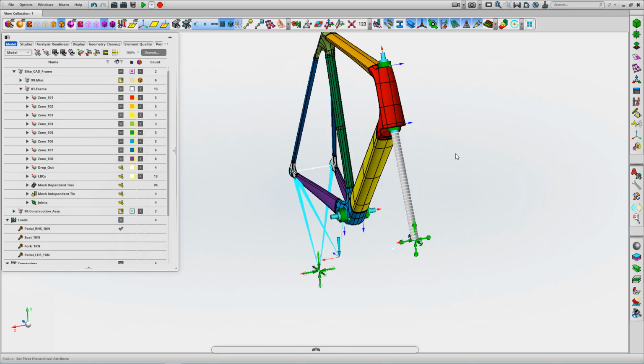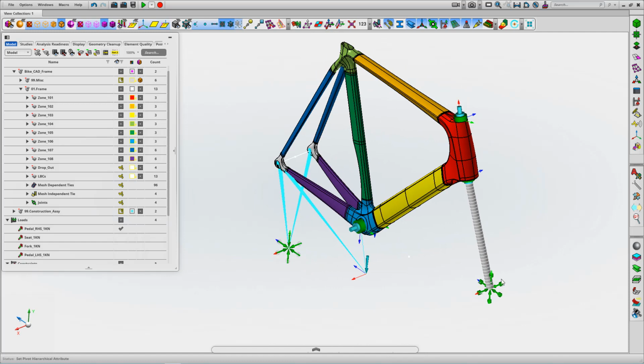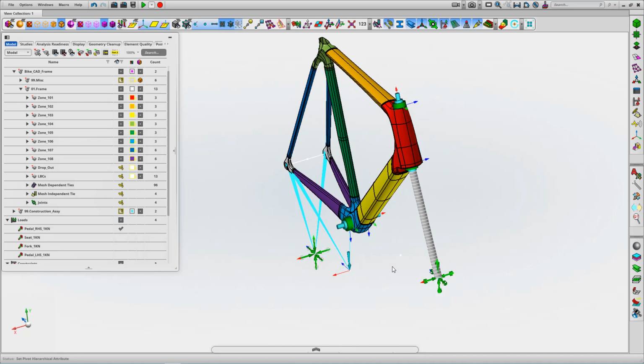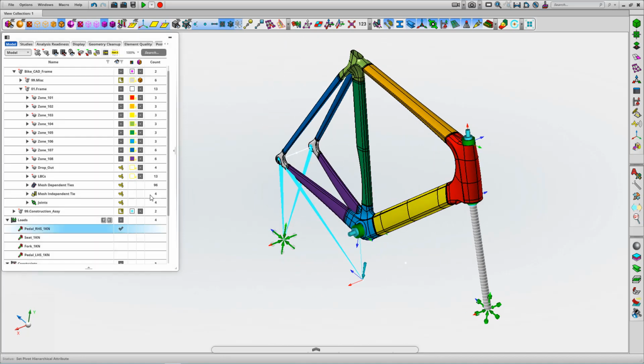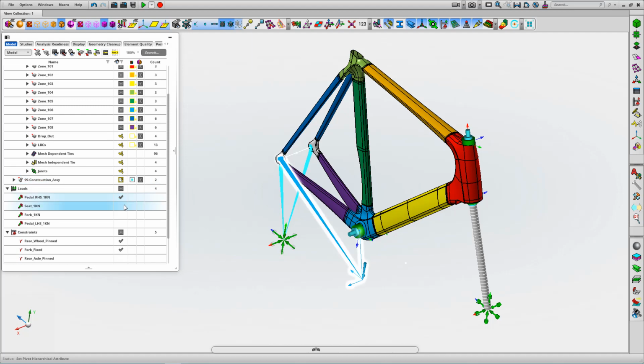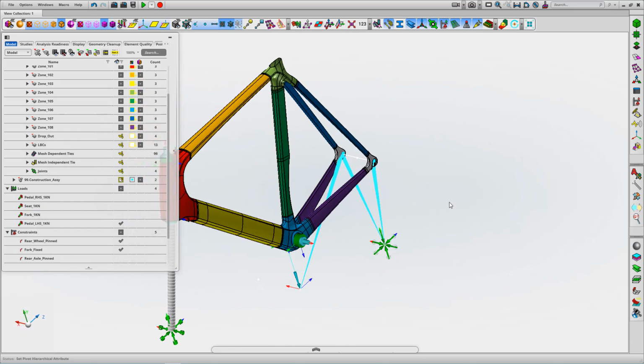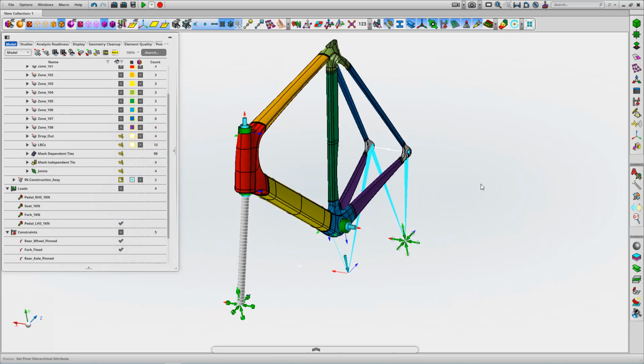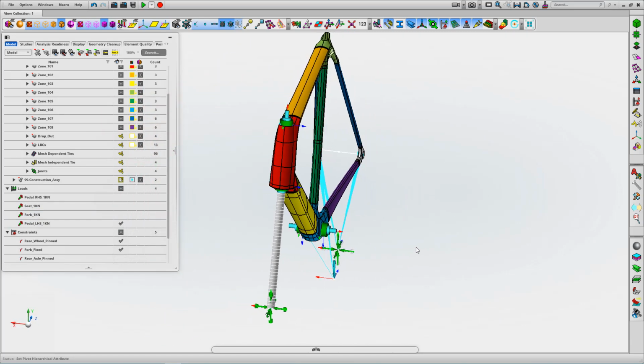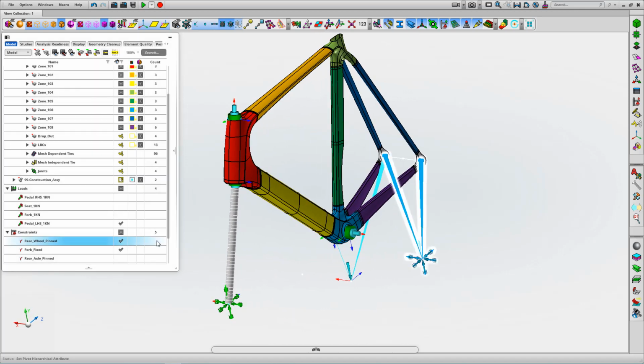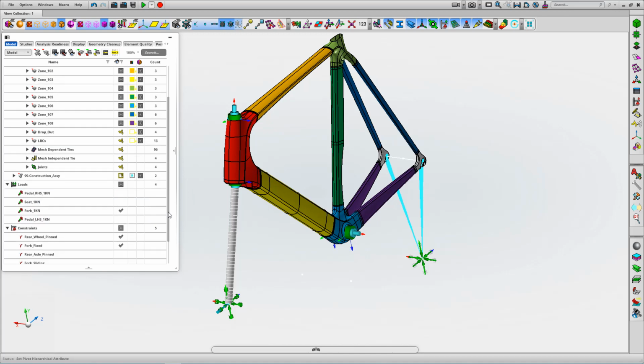So here we've got the fork fixed, a load applied through the right hand pedal, and then a constraint where the rear wheel meets the ground. And this is typical again of a standard ISO type loading environment. Okay, we can show the application on the left hand pedal. Okay, and again this is reflective of the ISO condition, and then cycle our way through for the fork load.